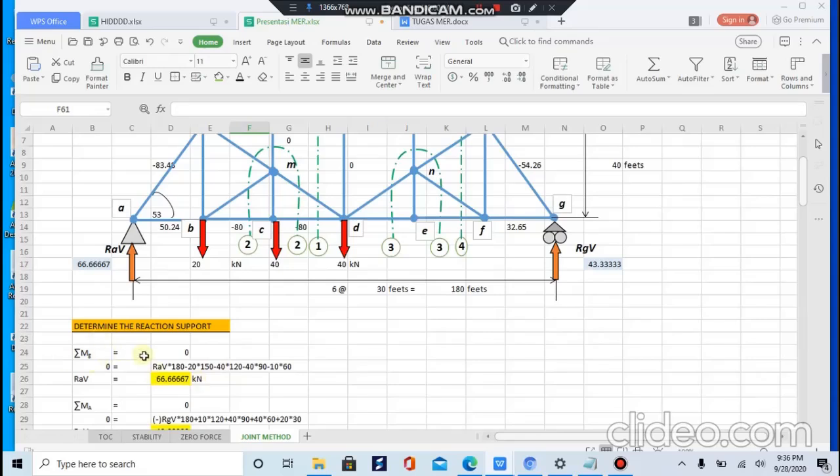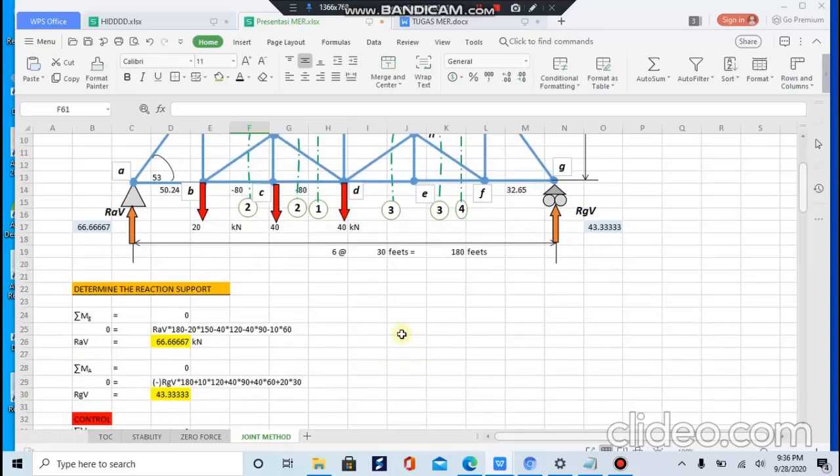The moment is a summary of the forces that work multiplied by a distance. You should underline that the plus or minus of a moment is determined from the force direction. If it is clockwise, it will be positive, but if it is anti-clockwise, it will be negative.